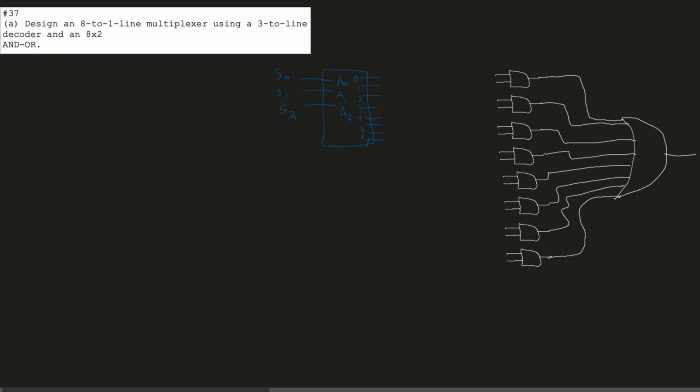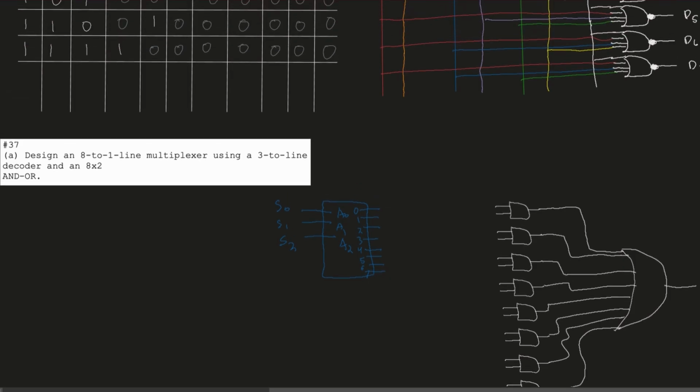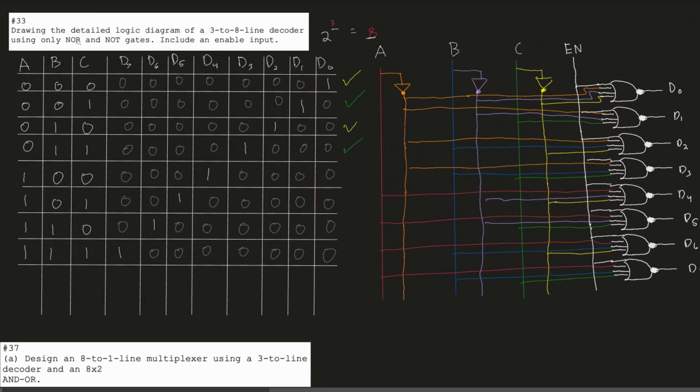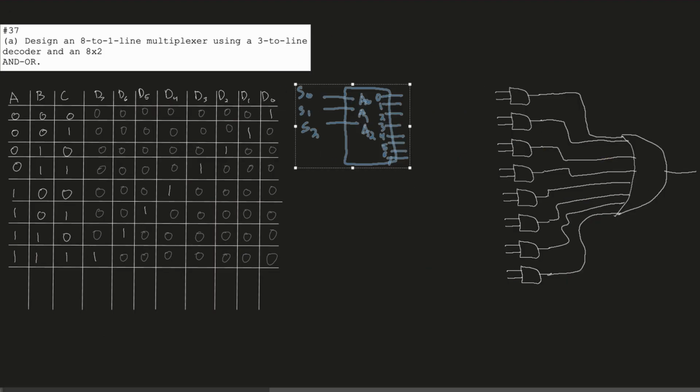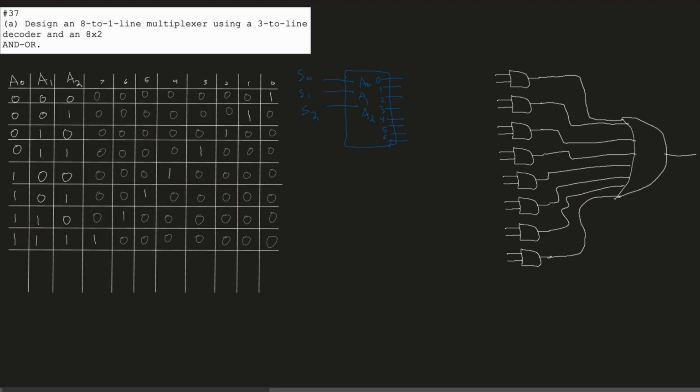And so each of these, if we were to demonstrate it by a truth table, we could see how this would be on and off depending on what we have. And from the previous problem, it's pretty similar. We're actually going to use this same truth table. There are a few things that are different though. Instead of having an ABC, we have more of an A0, A1, and A2, but that doesn't change any of the inputs. What does change though are these. So they're no longer D, because previously we were working with an encoder, now we're decoding. So we are going to have I7, I6, I5, I4, I3, I2, I1, and I0.